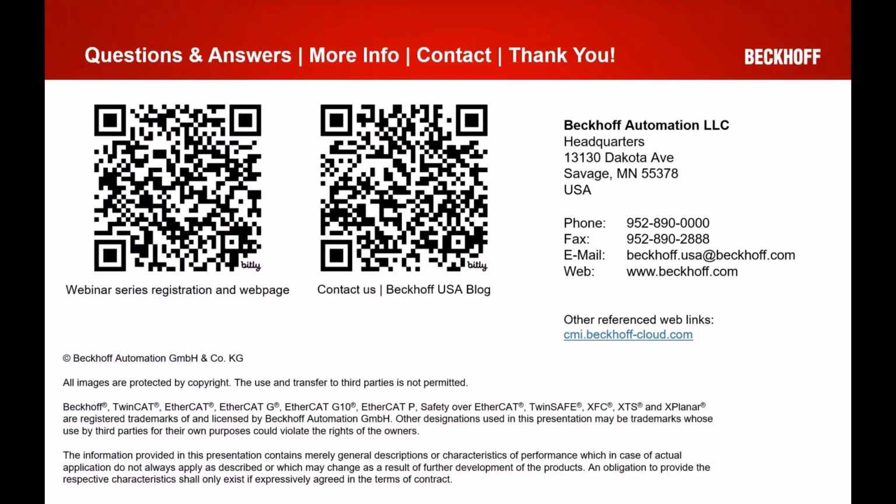Maybe someone that's helping out with the questions in the chat can drop a link to the documentation on that, but it's available on our InfoSys. It'll tell you exactly what to put in those attributes, and what the options are. For a while now, there's also been a hide option. So if you didn't want a variable in your PLC to be exposed to HMI, that functionality has been there a while now. Now we've built upon that and added some additional attributes that tie in with the HMI side.